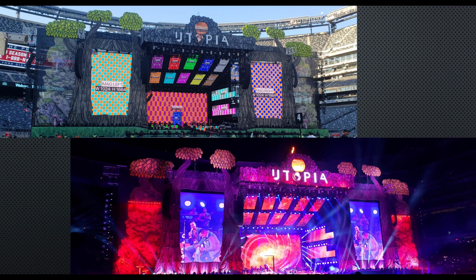Here's another example of portrait screens. On top, you can see the pixel map template, and this is how we test it normally. If it's pixel map screens, we would throw up our pixel map templates and check to make sure every pixel to pixel is exactly what we are seeing on the LED screens. And the bottom picture is where you can see the content. On the stage screens, obviously there's different content, different situations that they're going through throughout the show. On the side screens, it's portrait screens. So here's where they've used aspect scaling top to bottom and cut off side to side.